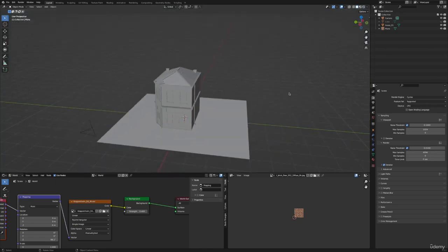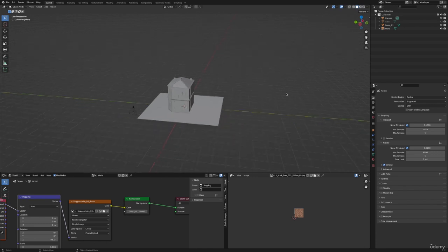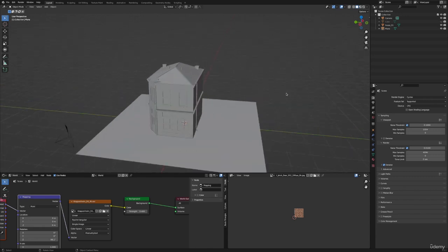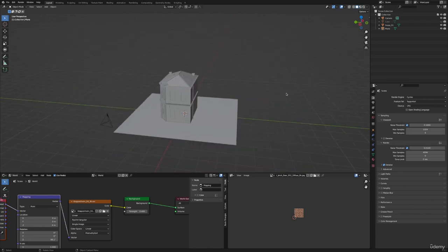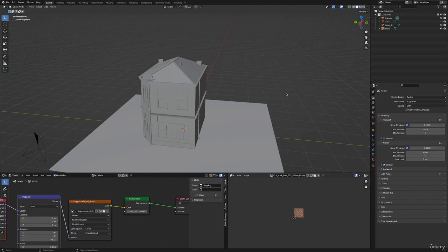Well, first of all, the same three types of object as in the fluid simulation are also valid here. That means we have a flow object again, and that's the object from which the particles of the simulation, the gas particles in this case, will flow out of. Then we have the domain. Firstly, the domain is the limitation of the simulation because the computer cannot simulate a complete world, obviously, that wouldn't work. And the domain is actually at the same time our smoke, or in the case of liquid simulations, our liquid. So the domain is not just the limit at which the smoke disappears or the place where you do the settings options, but it actually is the object that is being simulated itself.